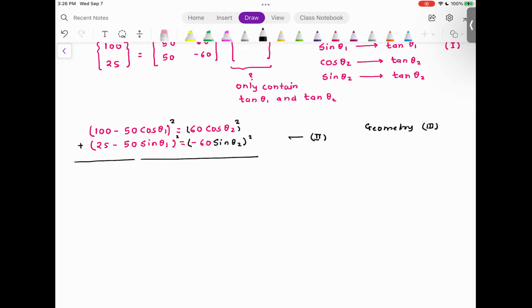Let me tell you, this problem is similar to the problem that we discussed in last class, but instead of 2 joints, now it has 3 joints. And next part is this. Let me tell you a philosophical approach in solving articulated robots. If you want to achieve X, Y, Z position and roll, pitch, and yaw orientation, there are 6 variables. So px, py, pz, theta, psi, and phi. So these are the end effector orientations.